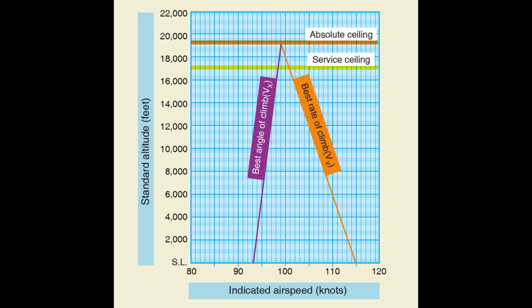If a climb is started from cruise flight, the airspeed gradually decreases as the airplane enters a stabilized climb attitude. The thrust required to maintain straight and level flight at a given airspeed is not sufficient to maintain the same airspeed in a climb. Increased drag in a climb stems from increased lift demands made upon the wing to increase altitude. Climbing requires an excess of lift over that necessary to maintain level flight.